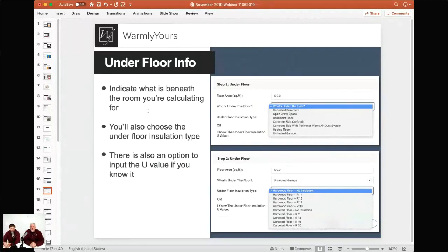And the good part about almost all of the further steps here, you always have an option to enter a U value for the insulation or that product or that window or the door that you're installing. So if you don't see your selection in the drop down, but you have the U value, just use the U value to type it in and use in the calculations. That's usually supplied by the manufacturer, right? Yeah.